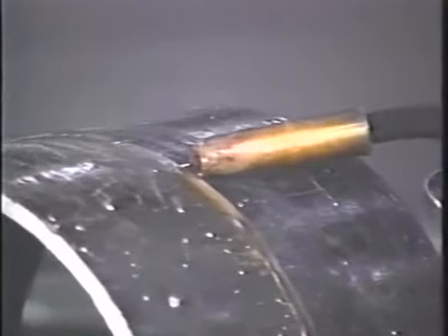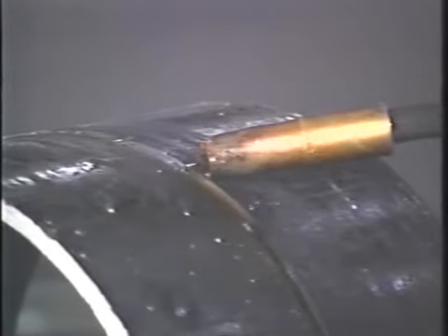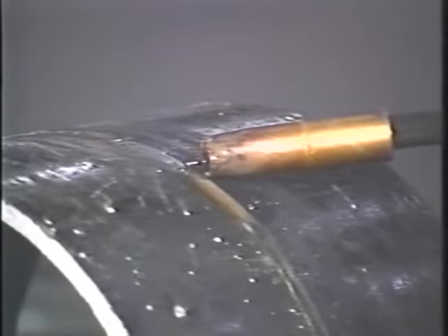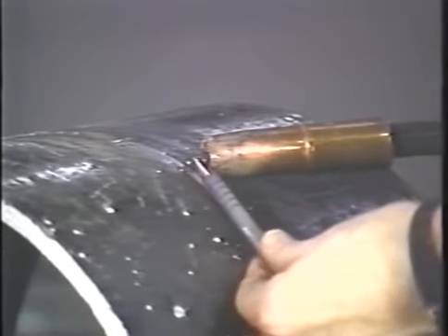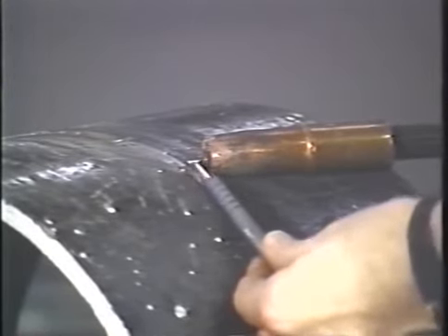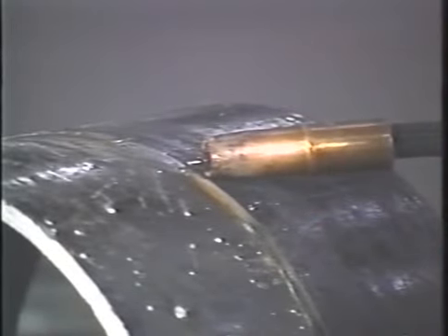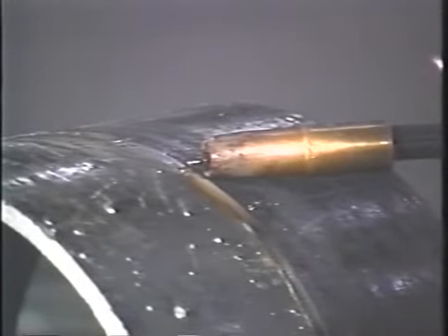It doesn't matter whether you're welding a pipe or a piece of sheet metal. You're going to use short circuit welding. And in short-circuit welding, particularly on quality work, on code work, and on very thin sheet metals, wire stick-out becomes critical. Notice on this pipe application that the wire stick-out is approximately 3/16 of an inch. By keeping the wire stick-out small like this, I can use the minimum amount of voltage, which on an application like this is usually around 17 or 18 volts.